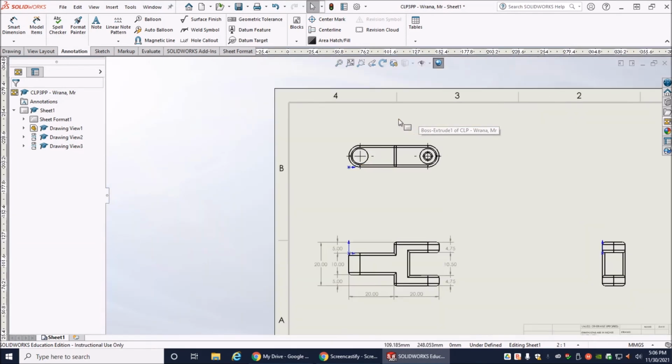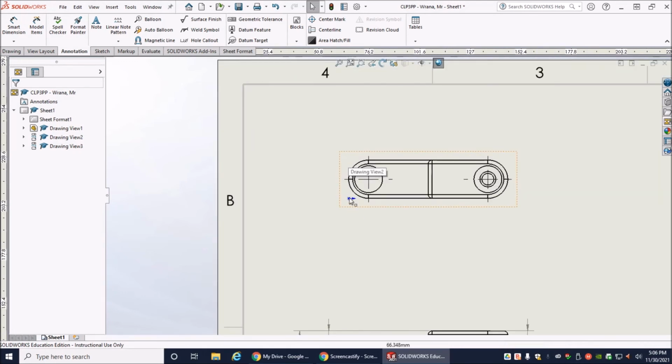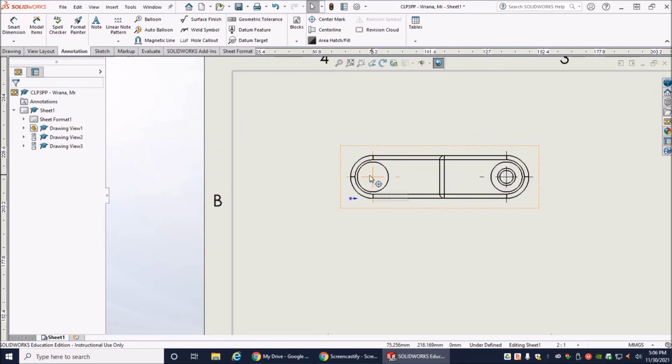Okay, the top one's going to be interesting because we just need a few pieces of information. We're going to center everything of our discussion on the circle, which happens to be a hole. I need to know where this exact center is so that I can run a drill bit right there if I'm using any type of aluminum or wood or plastic, so I can drill that hole for that pin. Same thing here on the other side. I'm not going to be too concerned about these other little holes, which is the access hole and the chamfer. I'm not going to worry about that right now. What I am going to be concerned about is just the actual circle and then its placement and its size.